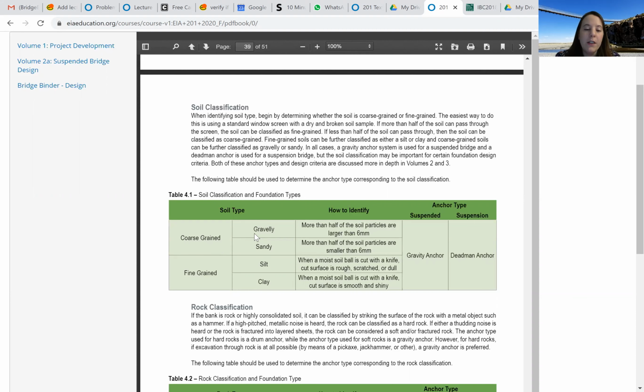You may run into a silty or clay soil, and these values in the manual won't apply, so that'll have to come from the bridge program manager in country. If they can tell you what the soil parameters are, then we might need to substitute in a different value than the ultimate bearing capacity that's currently provided.